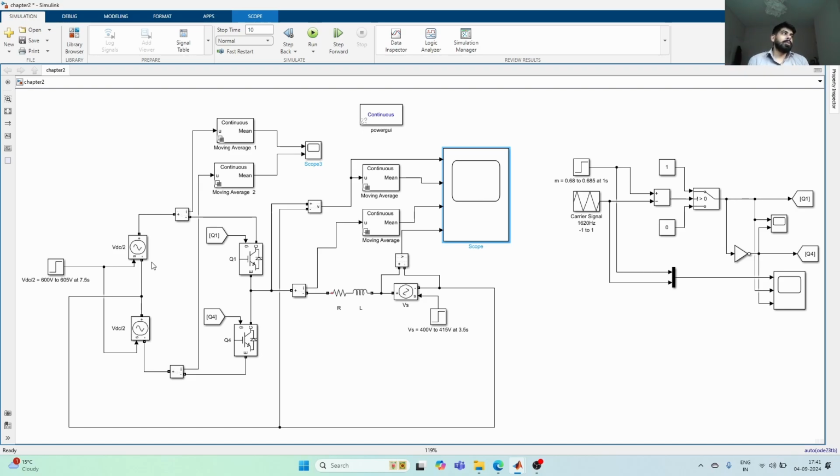So I would think about a control functionality where I, as a user, just give an input I reference, which would be, let's say, 1000 amps, and that control would change the value of m, the modulation signal, in a way that we get that reference value in the actual circuit, right? And how we can do this is basically a closed loop control. So we'll have a reference value, which will be a constant, user-driven value, where as a user I give that I want 1000 amps.